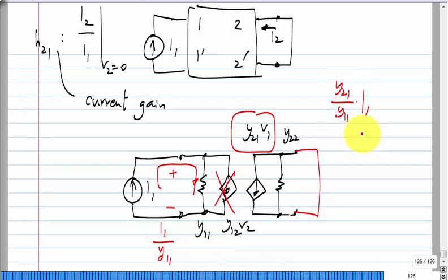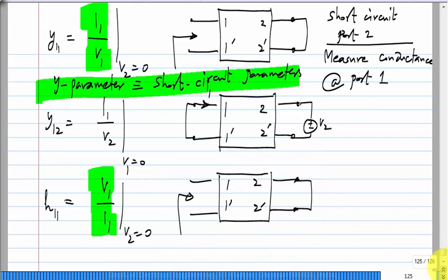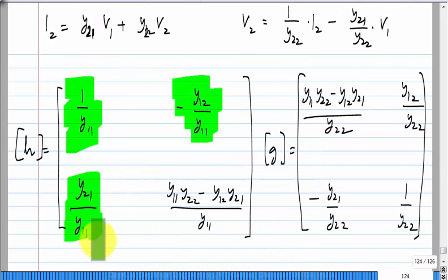I mean, all this is not a big deal. If you find it in the equations or this way, it just tells you why the circuit viewpoint can be important. So all that happens is this current gets converted to a voltage across this resistor, and then that voltage gets converted to current through this transformer. So that's why you see Y21 by Y11. So you can convert from one to other. I will take it as a G1. You should be able to do these calculations without too much difficulty. Any questions so far?